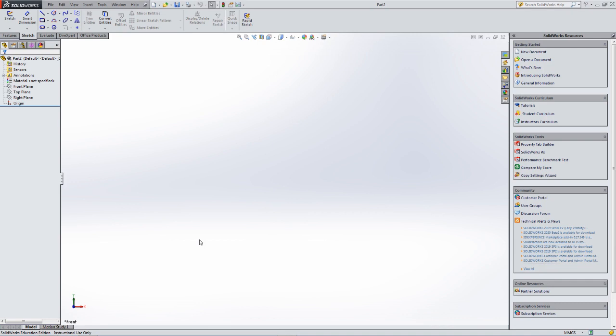Now, it's not a big deal. We have to keep track of the differences. We want to keep our X and Y axes the way they are normally defined for aircraft. We don't want to draw according to the SolidWorks orientations, because that would then be confusing when we try to do other aircraft things with our aircraft model. So let's just keep it this way. Realize that there are different names for the different views, and we'll just have to do the translation in our head. So this is a top view of the aircraft.